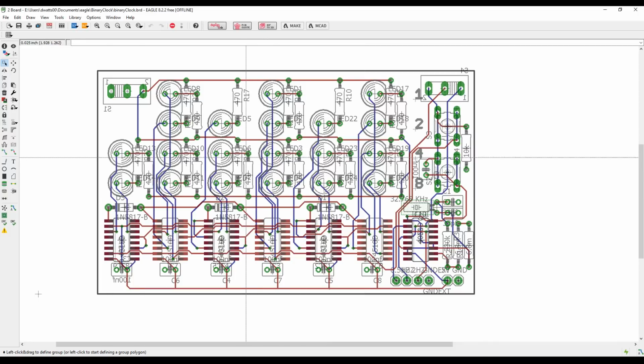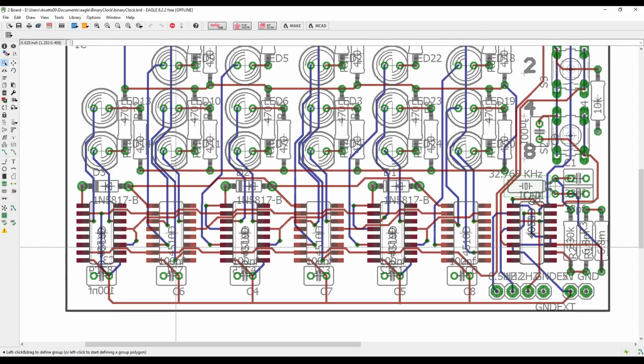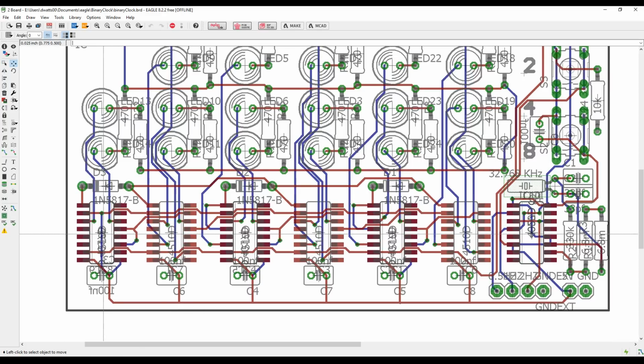And this is currently my layout, but it sucks. And what I'd really like to do is change it. But I wanted most, if not all of it, to be through-hole. And then I realized the through-hole packages for these 4510s and the, I think it's 4070, are just too large, and so the board's going to become really expensive. So I can overlay these, so I can put one on either side, which is what I've done here. So this is my, what is that, 4017? I don't think I remember what that one does.